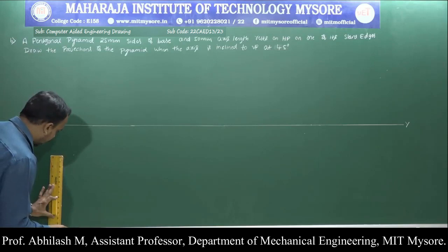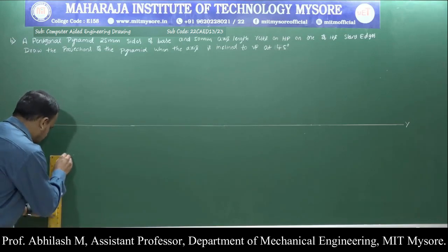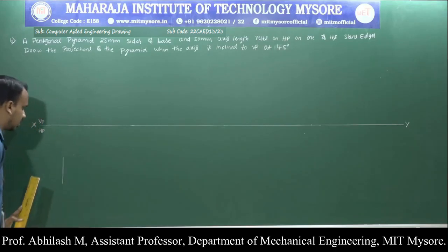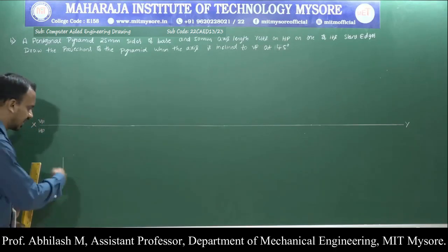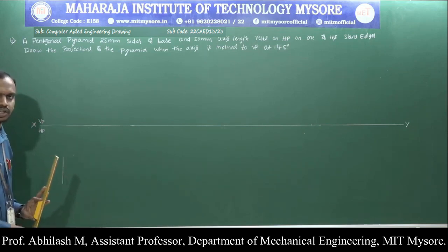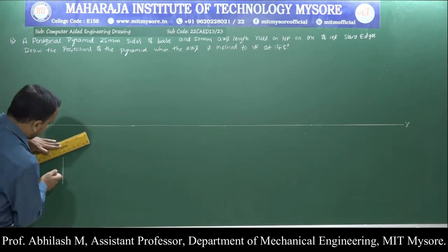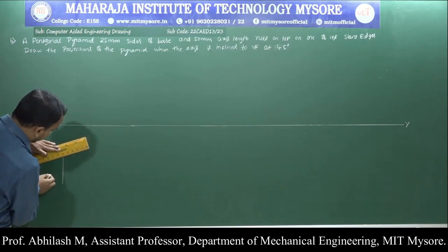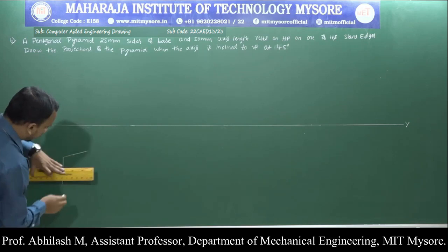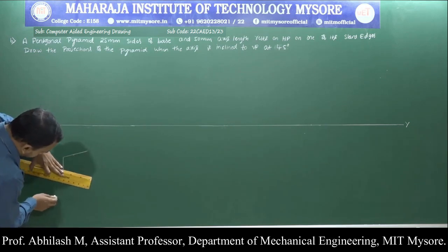First draw one of the base sides, next one of the sides basically. Next, you know that the angle is 72 degree in order to construct the other two sides. For that, draw the construction, take the angle and complete the construction of the pentagon, ensuring that it is resting on the slant edge condition.